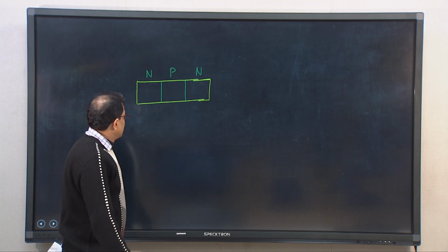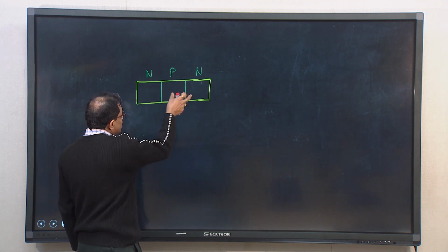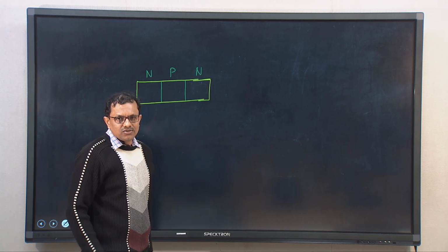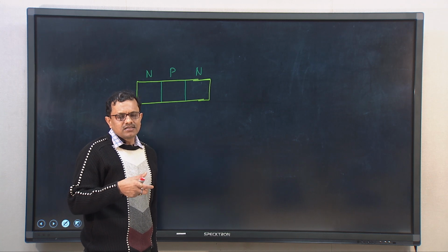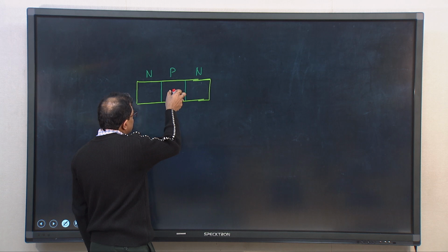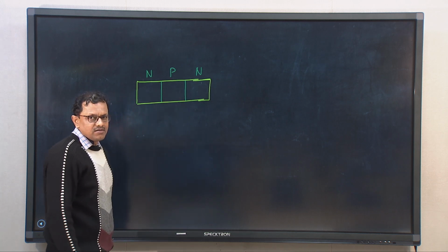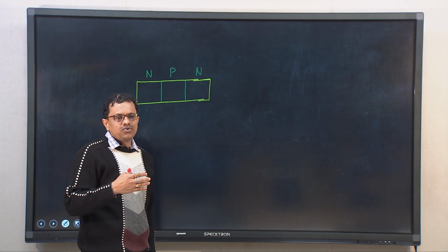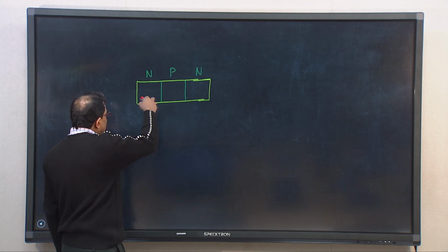Now, it is not that these 3 separate units are collected together to form this whole unit. So, this is a single unit itself, but the material property, material characteristics is such that this is n type doped, this is p type doped and this is again n type. So, in this p type semiconductor, hole is dominating, while in this n type electrons are dominating.